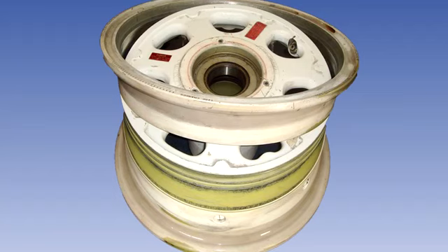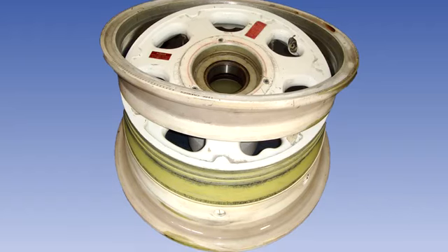Both the loose and detachable flange types of wheel are made with one flange integral with the wheel body and the other a separate removable part, which is machined to fit over the wheel rim. The difference between the loose and the detachable flange tyres is the method by which the removable flange is secured.